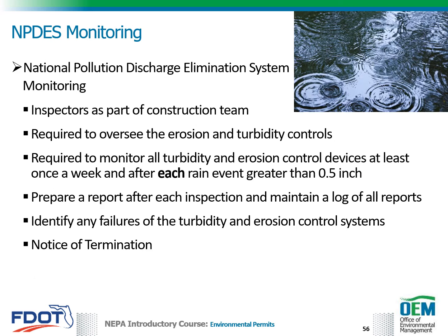Contractors for FDOT projects that include a Stormwater Pollution Prevention Plan, or SWPPP, generally include National Pollutant Discharge Elimination System, NPDES, trained inspectors as part of the construction team. These inspectors are responsible for the proper implementation of the SWPPP. In addition, NPDES inspectors may be required to oversee the erosion and turbidity controls in accordance with the Construction Project Administration Manual. The FDEP provides an excellent series of NPDES inspector training events throughout Florida. The training typically lasts for 2 days and concludes with a test.